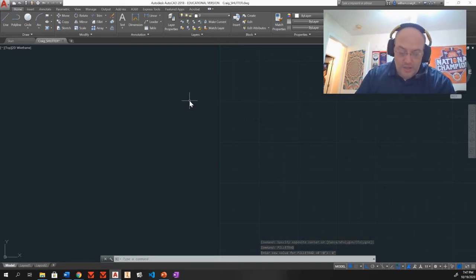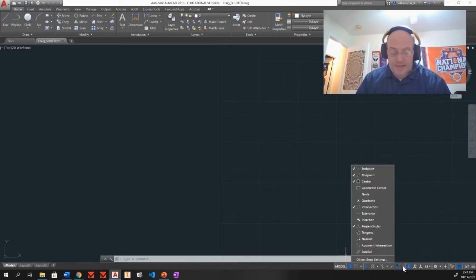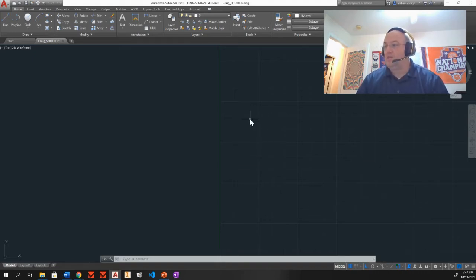Very good. So let's see here, another couple things, make sure we have set up in our procedural settings. We have the snap off, which is right there. I got that turned off, good. My grid is on, very good. My ortho over here, ortho mode is on, very good. And my O snap is on. So that's my object snap or O snap. And if I pull down my settings, as it says in my procedural setup, I have my endpoint, midpoint, center, intersection, and perpendicular. Everything else is off. So I'm good to go.